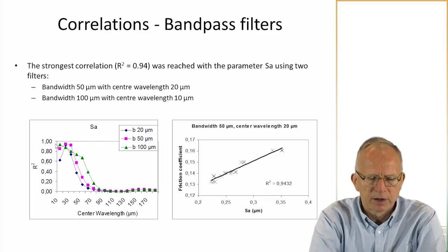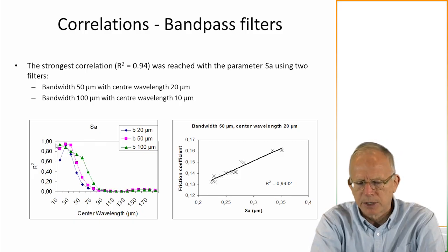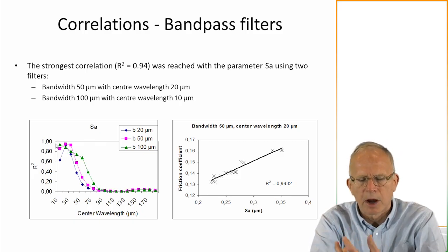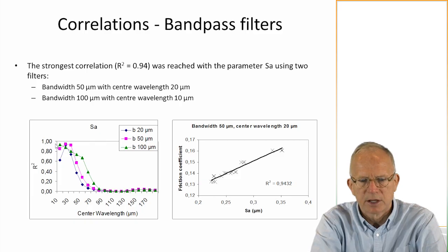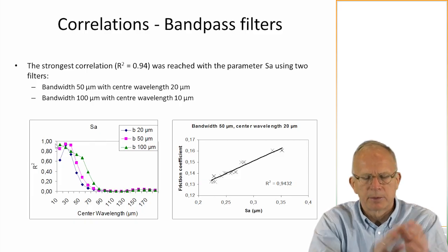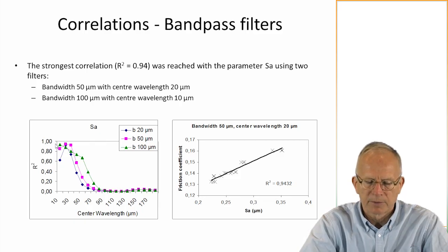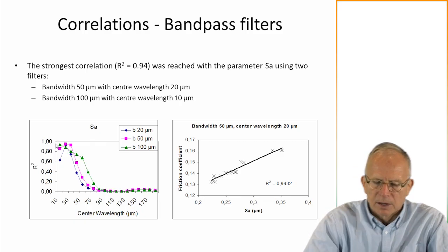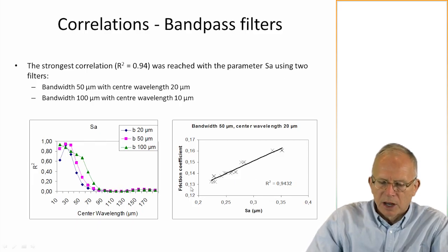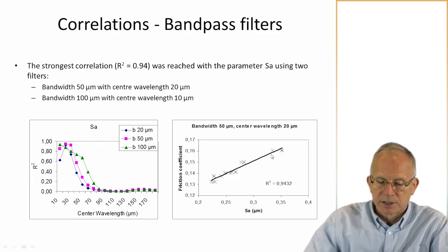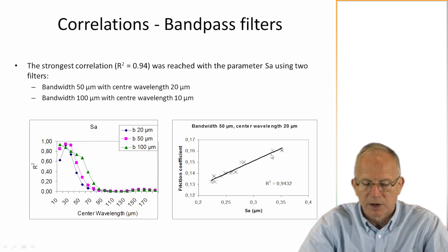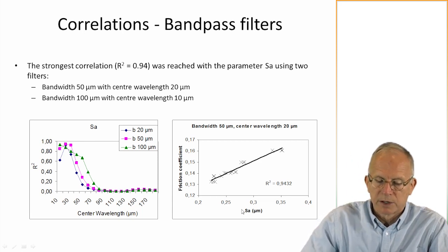So what we've done essentially, in some ways, is turn average roughness into a kind of slope parameter by taking such a narrow chunk in the spatial frequency domain or the wavelength domain. So here's the regression line, and then this could be used, as I said, in design when we're trying to get a correlation between a design parameter and an FR.